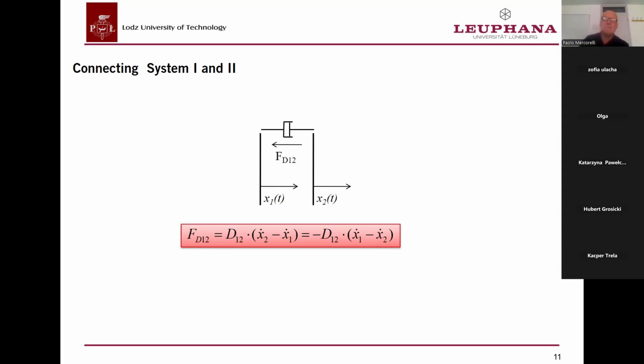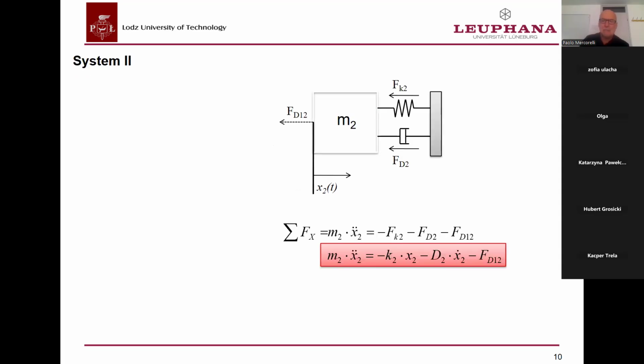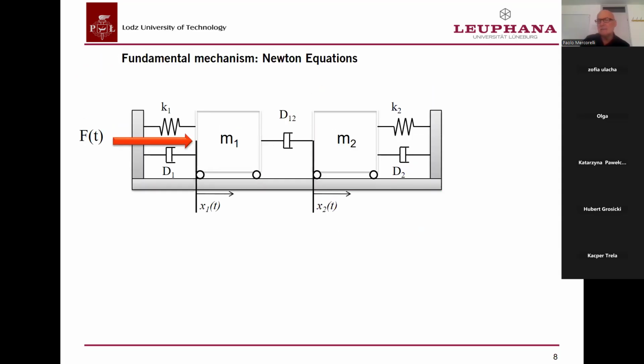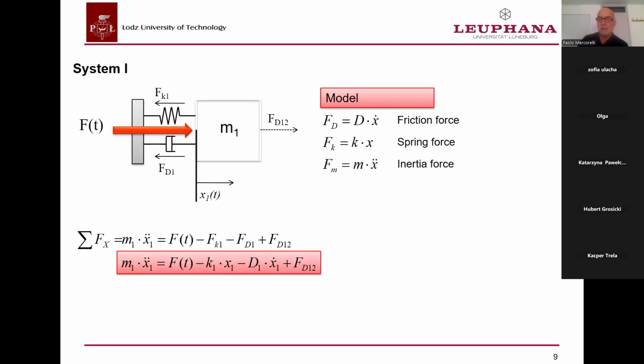In order to understand better, probably I would like to come back here because I copied this material from a book. Look at this. If I move left the mass m1, assuming that I fix m2, I have the reaction. Let me say the reaction on the mass m1 in accordance with the friction force is minus d12, which multiply x1 derivative, in accordance with the model which is here.